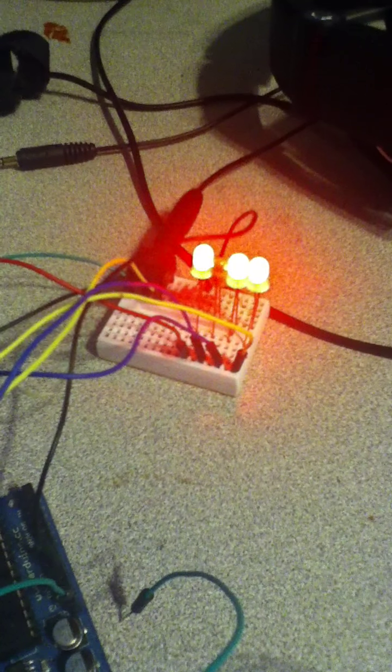If you look in the video description, you can find source code, and I think I will post some compiled hex files that you could try to upload. I'll also tell you which pins are what, because you can't really see it very well here, which pins on the board are for the sound and the LEDs. But if you do try this yourself, don't hook the LEDs directly up to the pins or they will burn out.